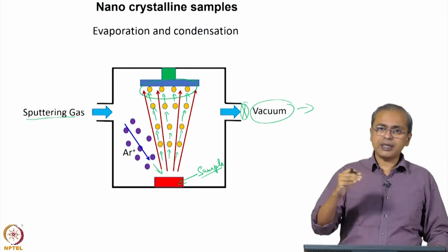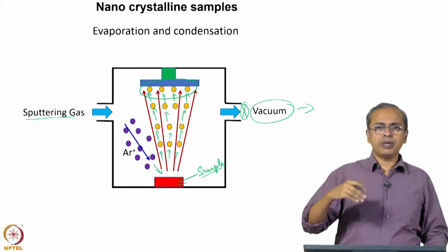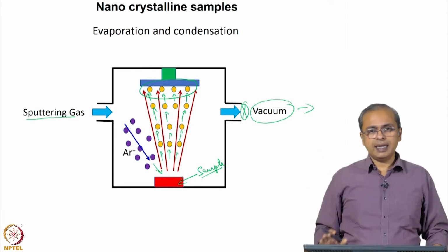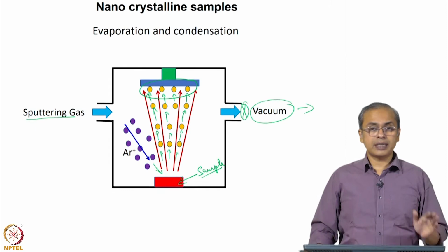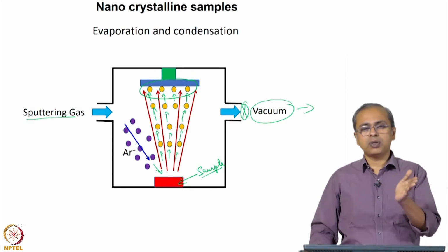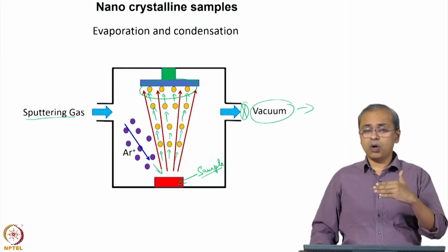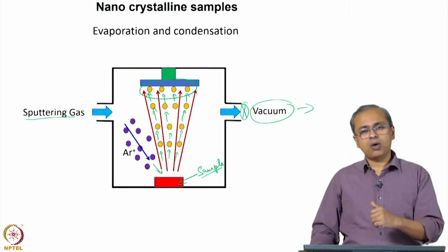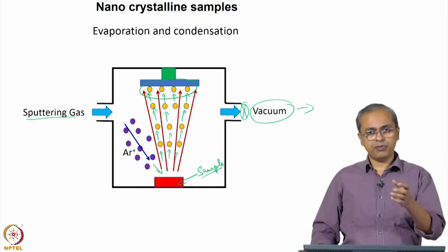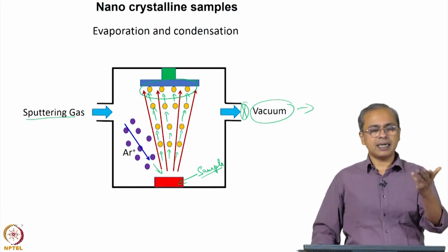On the other hand, if you use sputtering process or you use the E-beam evaporation, even after you reach the low vacuum, you have to continue, it is a very slow process. It is gradually removing material, and that material eventually ends up on the substrate that you are condensing. So, it takes some time based on how much sample you want to evaporate. In the thermal evaporation process, the boat remains intact, and whatever sample you put inside almost instantaneously evaporates. So, if you put a few grams, all of that is in vapor form immediately, it condenses.